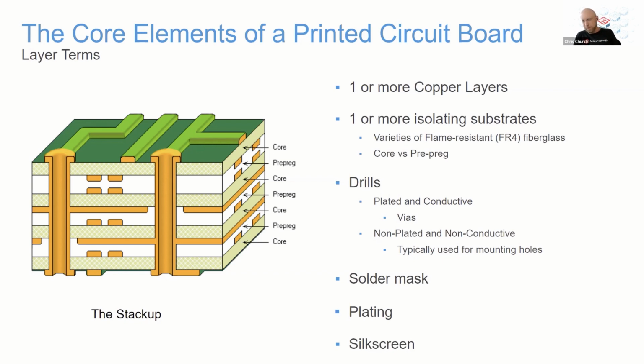Another very common one you'll see is ENIG. This is an electroplating form, which is electroless nickel immersion gold. And that is very flat. Each pad will be covered in a soft gold. And in all of these cases, the goal here is to protect the copper as much as possible while minimizing the impact on the solderability of that. So one of the things you will see is a lot of higher end boards will prefer to use something like ENIG or OSP, something that is plated on there, or EPIG.